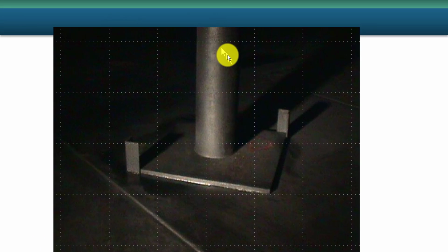Here's a picture of one of these columns. This plate has to be free to move up and down in these guides, a couple of pieces of angle, because all tanks settle, and when that settlement happens, you don't want it to pull down or push up on the roof. So it has to be free to move like this, and therefore the area underneath this plate is part of the steel bottom and it can corrode out.